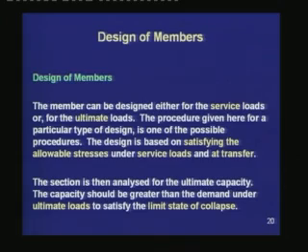This is different from what we had studied for reinforced concrete. For reinforced concrete, the design is based on the ultimate strength being greater than the demand under ultimate loads. But for prestressed concrete, we are adopting a different approach. We are designing a member such that the allowable stresses under service loads and at transfer for the concrete are satisfied.